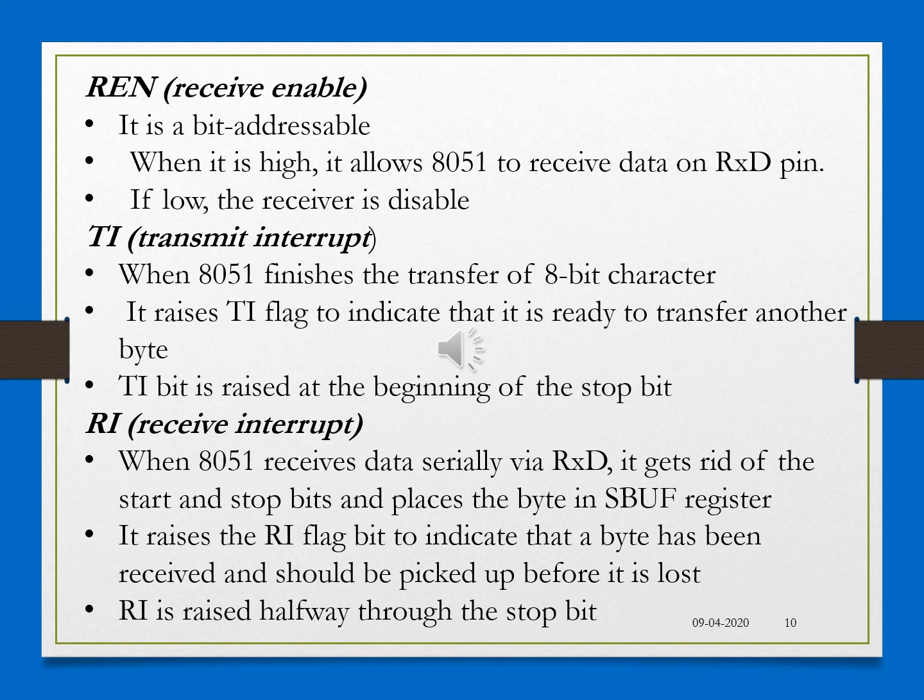Why? Because see, transmission can be controlled. Reception is not controlled. When you are transmitting data, it is you that will be sending the data from the 8051 based system to any PC. When there is a connection between the 8051 microcontroller and any other PC, reception is not controlled in the sense that if the PC is sending data, it would be coming via the RxD line.